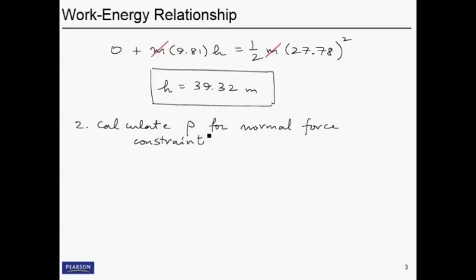So this is a kinetics type problem, so let me write the free body diagram over here to the side a little bit, and we're going to write this exactly at point B. So here is the car. It's got some wheels on the bottom. Now we're going to consider this thing to be a particle, so we're not going to consider the size or the distribution of mass. We're just going to give it a single mass, which is m times g, that's the weight. And then up here we have the normal component of force, and this is really just going to be 4mg.